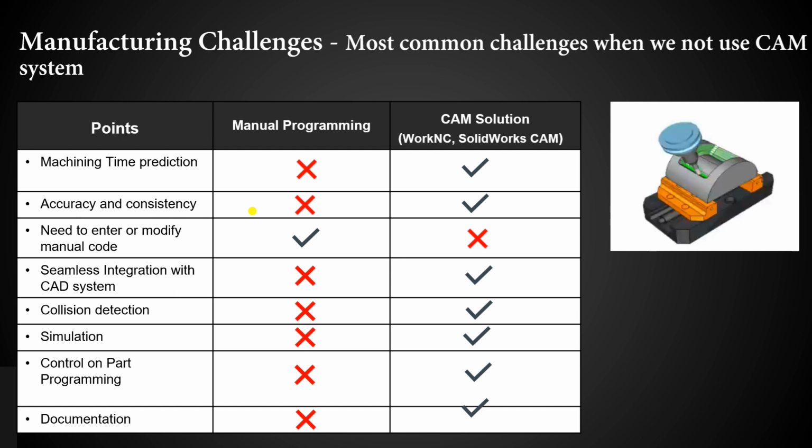After that is collision detection. Suppose you generate your program, after that you can detect your collision. Collision means an accidental case. Suppose you have to clear your holder above 55 mm, but your program is for 54 mm.